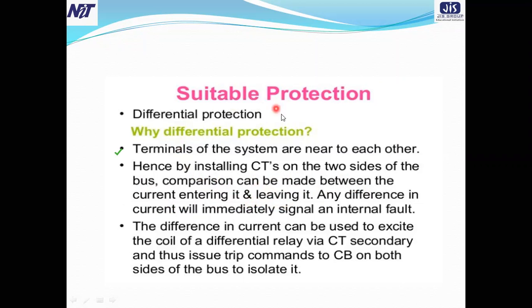Okay, so you know that in differential protection we can connect CTs on both sides of the bus. Installing CTs on both sides of the bus, we can compare the amount of current entering and leaving it. So that is one of the reasons for using differential protection. Any difference in current will immediately signal an internal fault. That is actually the property of differential protection.